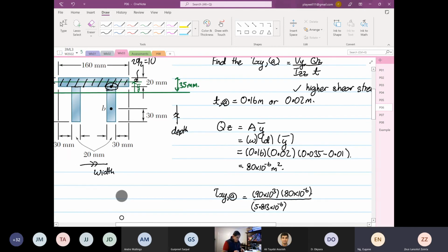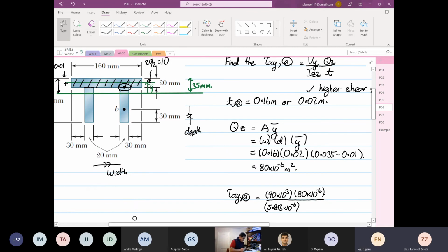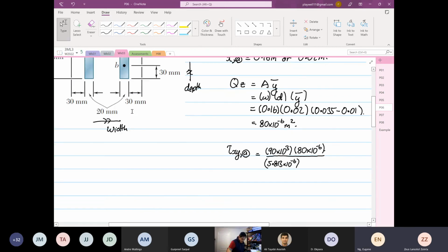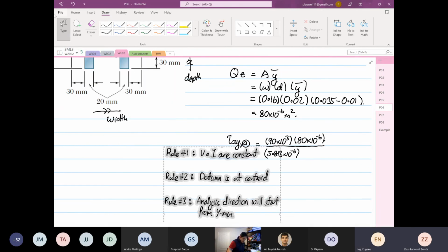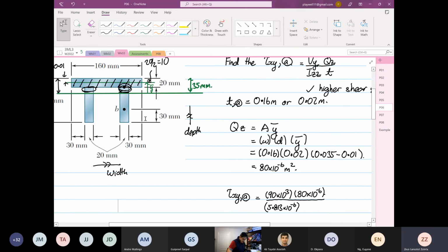You look at point A, the thickness. The thickness is shared on both sides. What do I mean? You have to consider the thickness over here and the thickness over here, twice. Because when the shear flow comes down, now I'm going to construct the shear flow. This is the construction of shear flow.